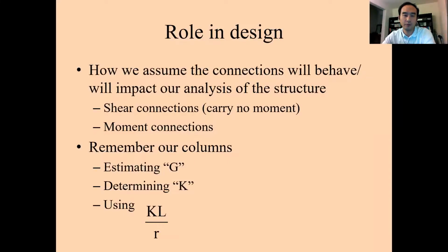For example, we talk about the column. In the column analysis and design, we use effective length factor that is based on the boundary conditions, right? And that boundary conditions in reality is going to be related to the connections. And so I'm going to talk about these two, shear connections and moment connections, in a minute, but that's how we can classify the connections in general, combining both the bolted connections and welded connections.